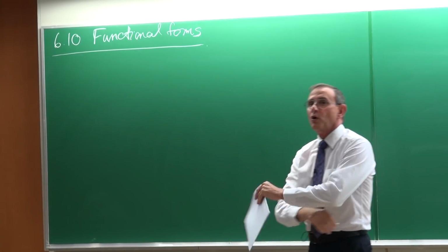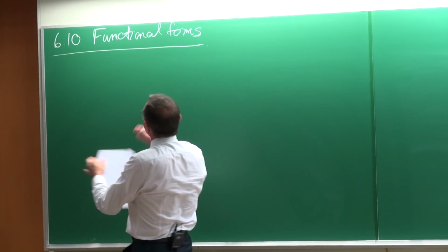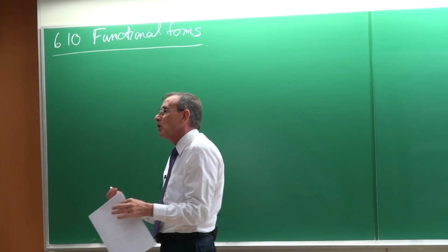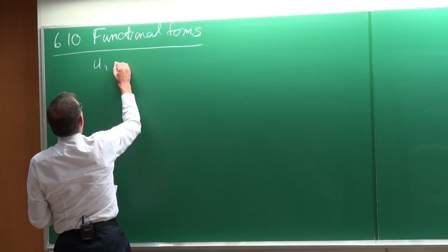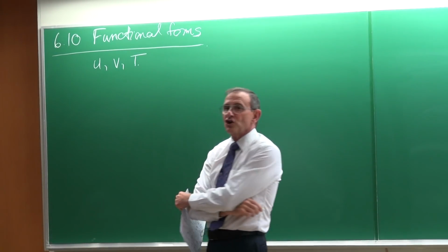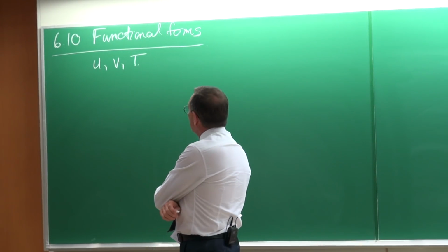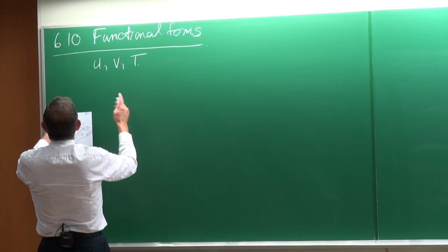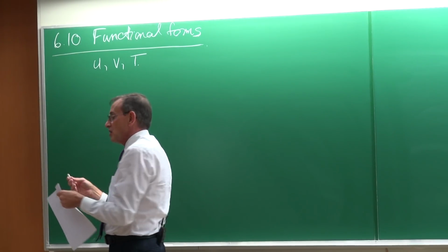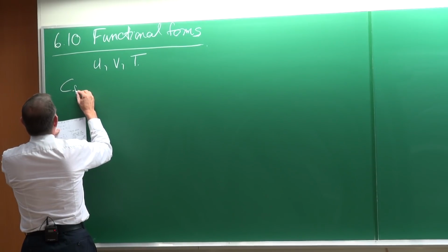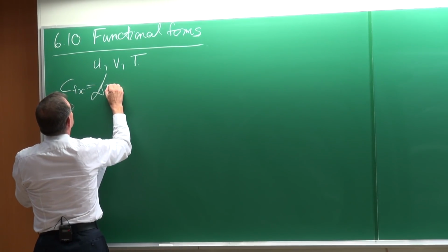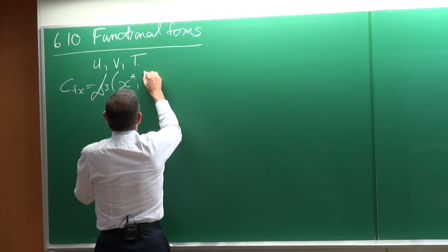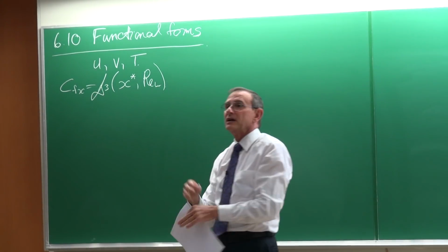Okay, so the most important part of this paragraph of the textbook is that it actually shows that in terms of the fundamental equations, the continuity equation, the momentum equation, and the energy equation, there are three variables that in general need to be solved: the velocity in the u direction, in the y direction, as well as the temperature. And these equations can then be rewritten in a non-dimensionalized form so that you can show that the friction coefficient is a function of the non-dimensionalized distance x as well as the Reynolds number based on a characteristic length L.